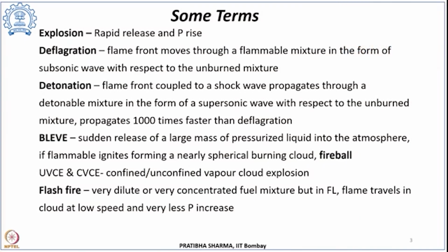Let us first understand certain terms before we see the different types of hazards. There is a difference between fire and explosion. Explosion may not always lead to fire, or fire may not always lead to explosion. The term explosion is used when there is loss of confinement. Initially it is confined, and if there is an unusual pressure rise and then a release of the fuel from the containment vessel, then it is an explosion.